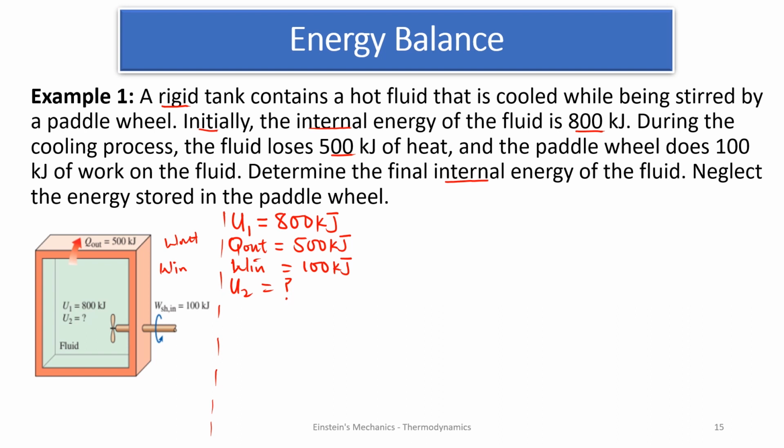Now we have heat, we have work, we have initial and final internal energy. Do you remember this equation? The total energy within any system is the internal energy plus the kinetic energy plus the potential energy. Are we good? So we are going to use this equation and let's make some deductions. From the question, the tank is rigid, and a rigid tank means it is stationary.